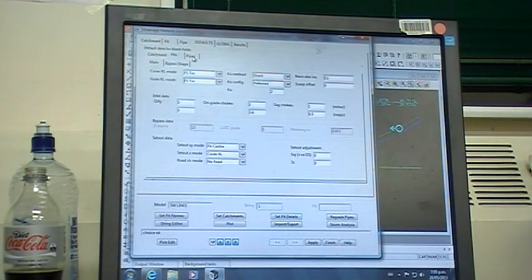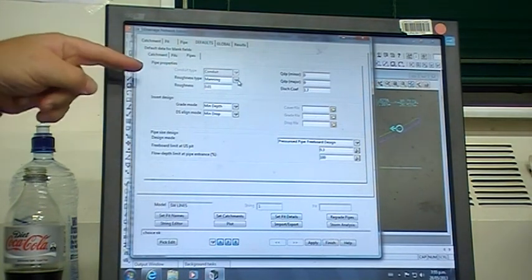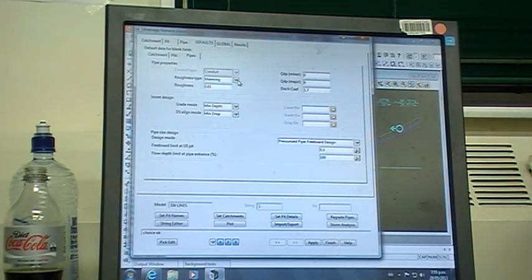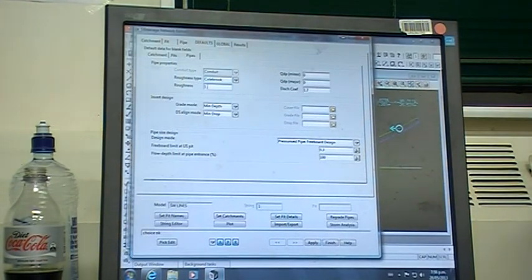The last defaults tab is our pipes. Now this is something. One of the stipulations in the assignment is that things have to comply with council standards. Definitely the council standards we're using, and in fact 99.9% of them, ask for Manning for open trapezoidal type channels, overland flow, but for pipes they require Colebrook-White. And the roughness we're going to use is 1.5 mils.